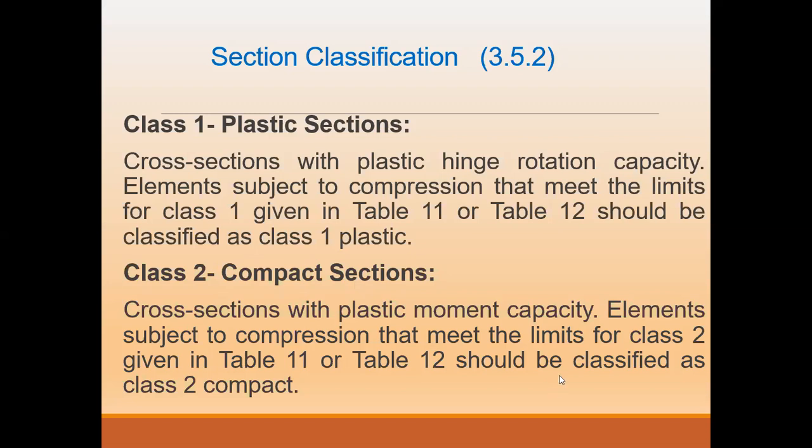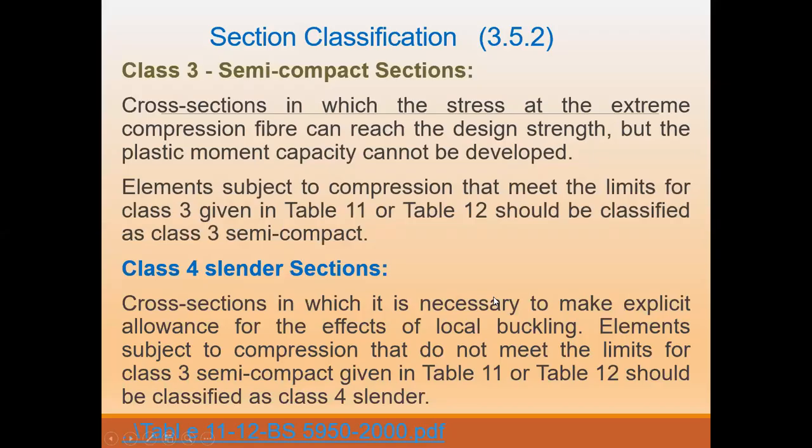The third one is called the semi-compact section. So the structural behavior of class 3 is that when they're subjected to stresses, the extreme fibers which are under compression normally reach the design strength.